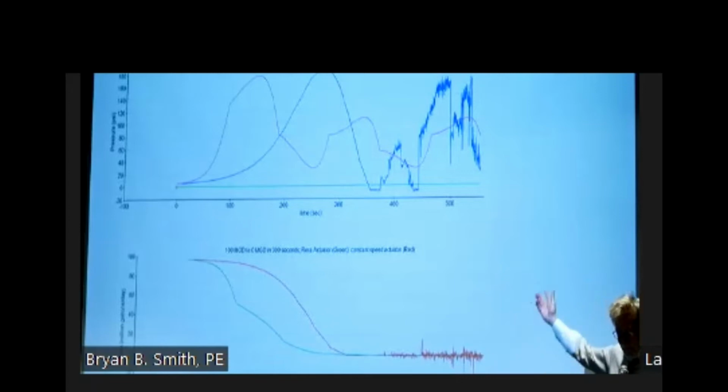Well, we already know what happened in closing the valve in 5 minutes. So using computer software in a 2-stage closing, I'm able to close the valve very quickly and then slow it down based on the critical velocity and the wave speed within the system. So then I get the purple line. You can see I close the valve very quickly, and then the second stage, I slow it down, keeping the high pressure lower and the low pressure higher to protect the piping system.